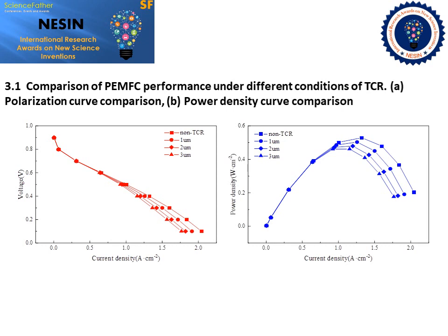And under the cell current density of 1.2 condition, the cell power density of the PEMFC decreases by 3.76, 8.47, and 15.46% when the surface roughness of PEMFC components equals 1, 2, and 3 μm.